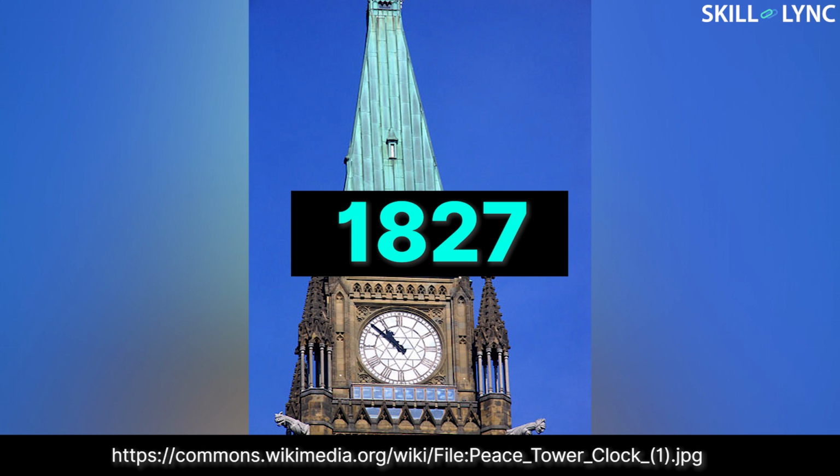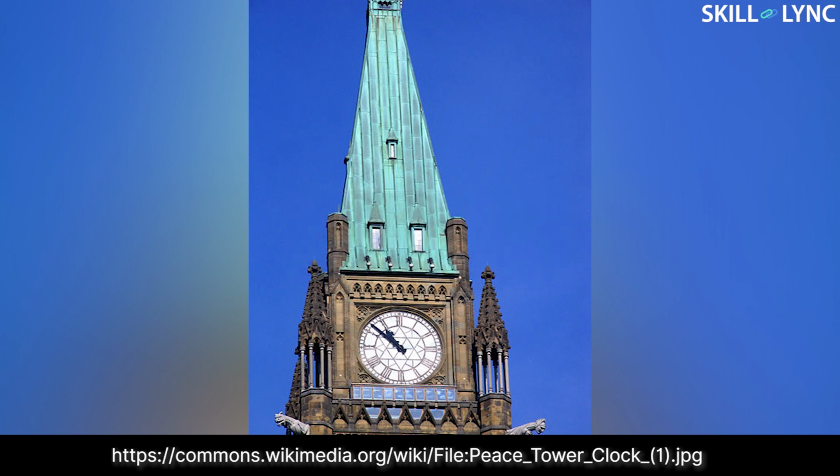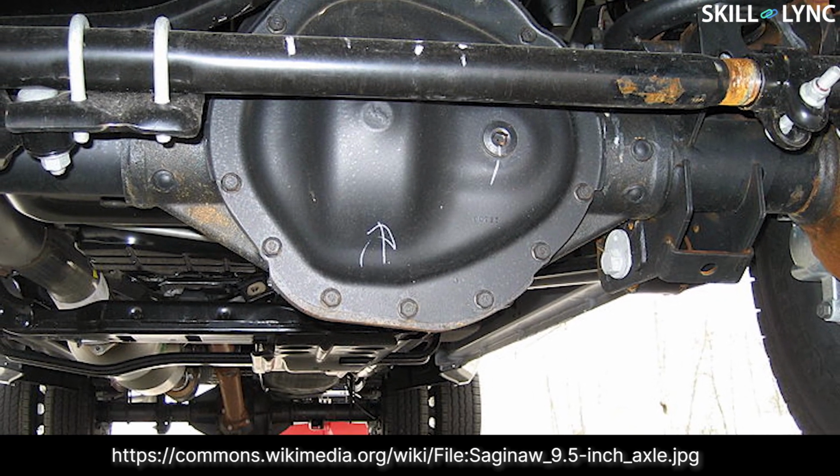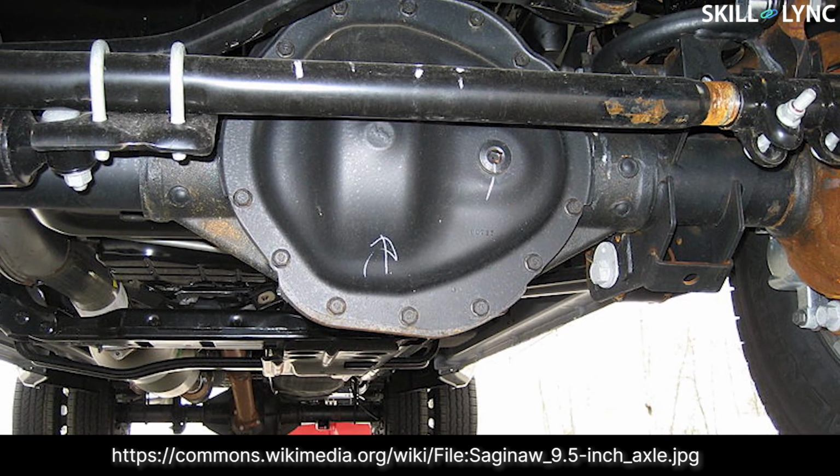called the differential. The differential gear was first patented in the year 1827 by a watchmaker and was used in tower clocks. It wasn't till the end of the 19th century that differential gears were used in automobiles. A differential gear system is a gear arrangement that permits the transfer of power from the drive shaft to a pair of driving wheels and enables them to rotate at different speeds. A differential will be located halfway between the driving wheels connecting their axles.